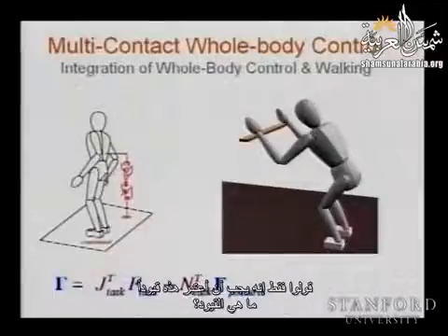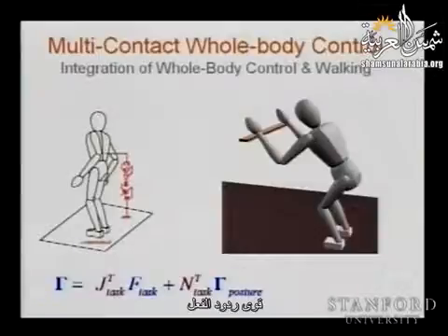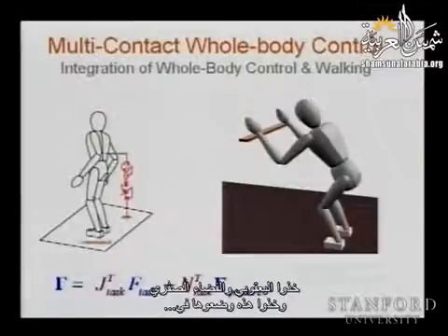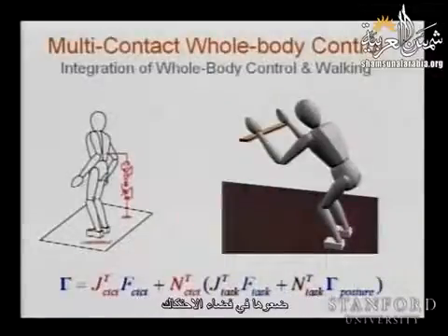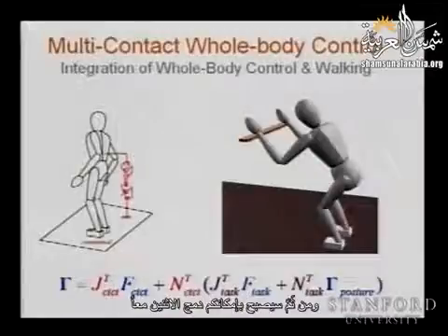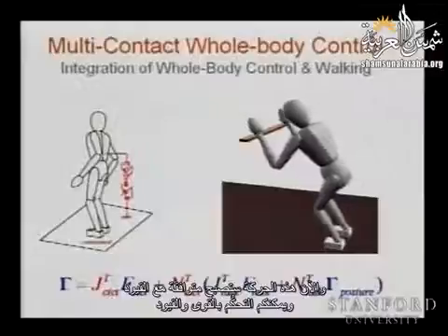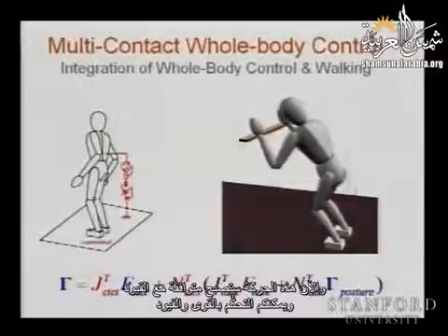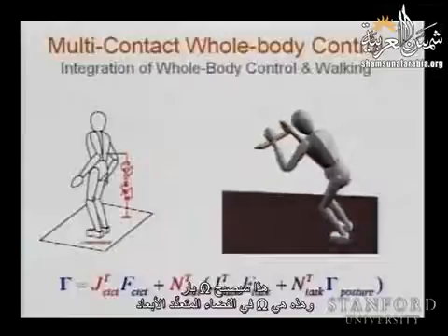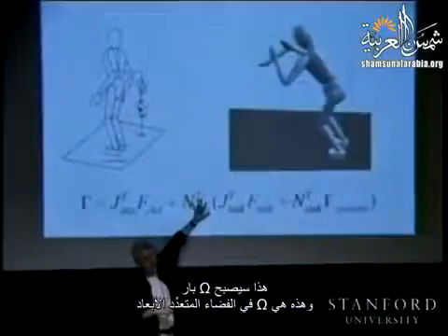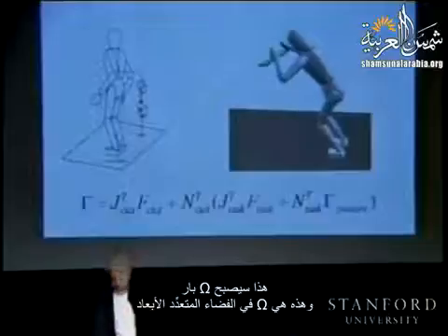Well, just say it. Say, I need to treat these as constraints. What are your constraints? These normals. Take the Jacobian, take the null space, and take this and put it in. Now you know how to do it, right? Put it in the contact space. And then you are able to bring the two together. And now this motion will be consistent with the constraints, and you can control the forces at the constraints. If you remember in the beginning of the class, we talked about omega and omega bar. This will become your omega bar, and this is your omega in the multi-contact space.